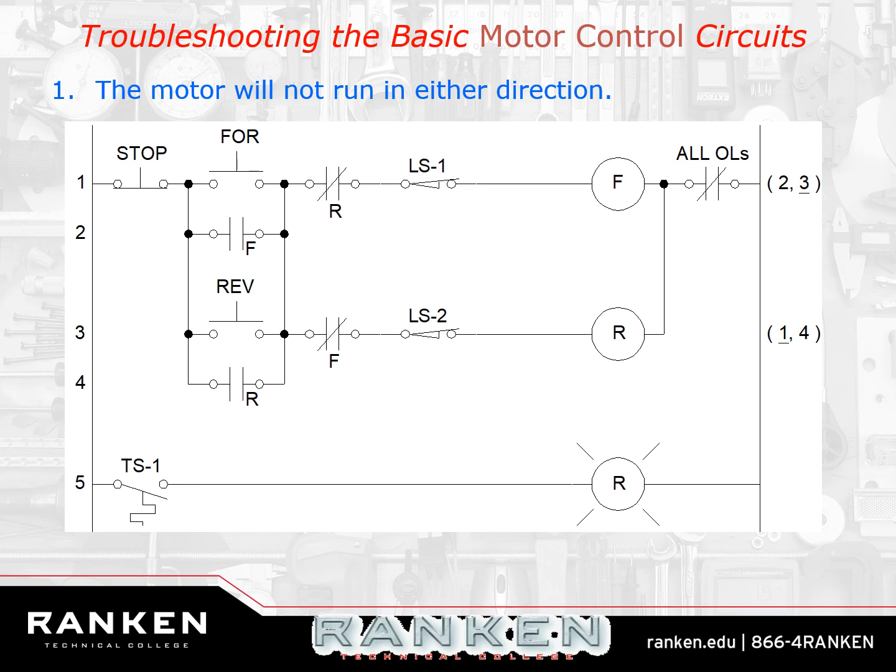What control device do they have both in common? Stop and start. Well, the stop button would keep both of them from coming on, right? They both have limit switches. Yeah, but what are the odds that both limit switches are in the open position at the same time? Probably not very good, right?